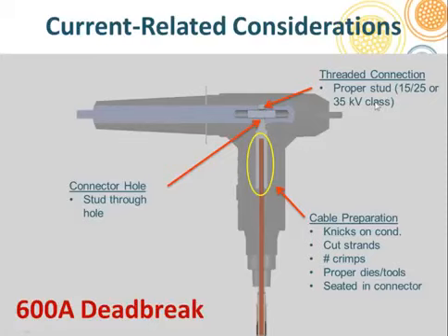Also, there are several specialty studs in some specialty connectors out in the field. These studs are not even the same length on each side. If they're used in a non-special application, and they're put in the wrong direction, they will bottom out on one side of the hole, and again, the torquing will not allow the two faces to come together. It's absolutely paramount that the faces of the lug and the bushing mate.